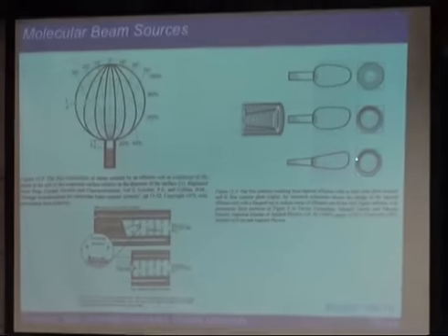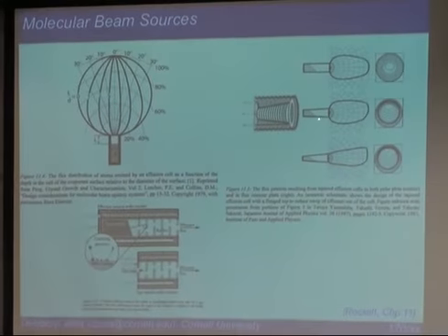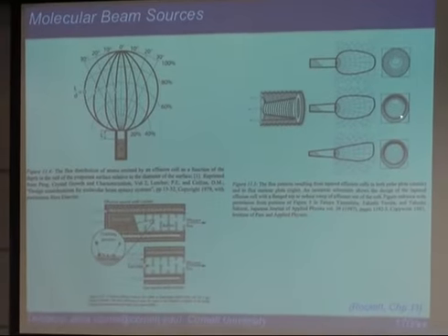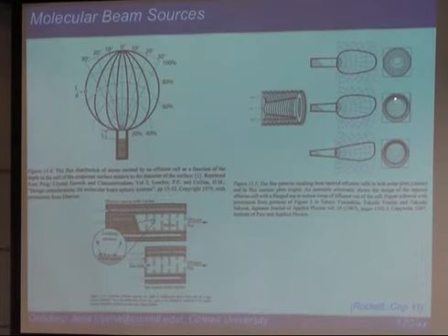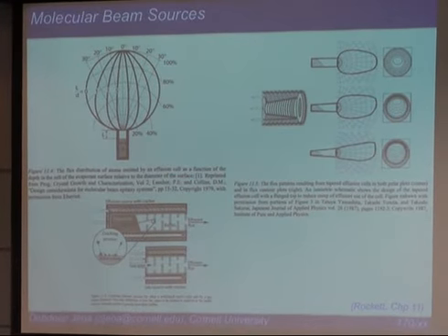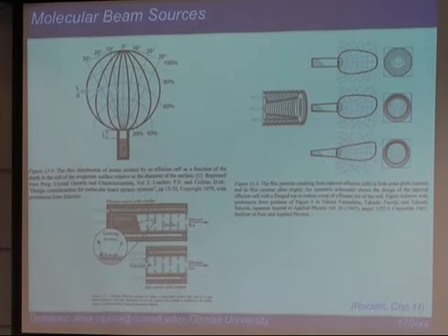So this really tells you that for certain geometries, for example, if you grow a laser here, you may have a little bit more gallium than here. That's really what it means. The amount of material that reaches there. There are some other elements. So we talked about elements that are easy to evaporate. For ones that are hard to evaporate, typically you'd be using an E-beam source, right?